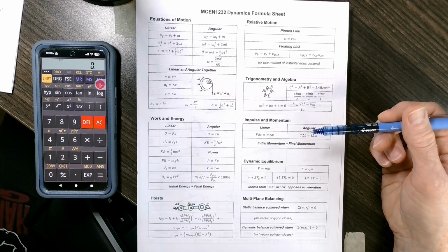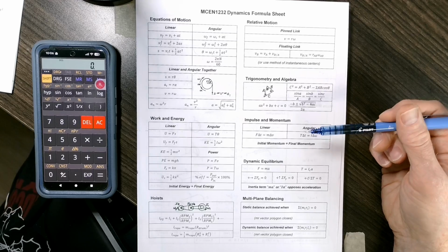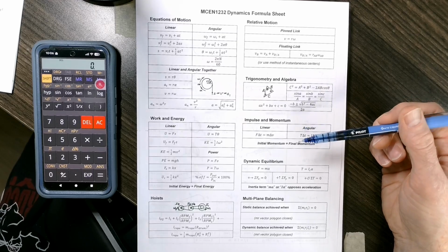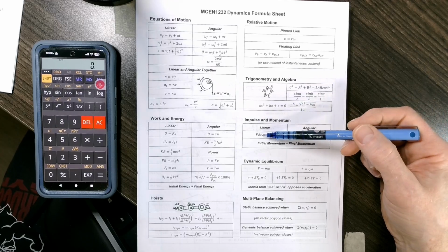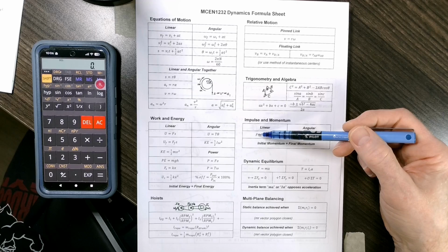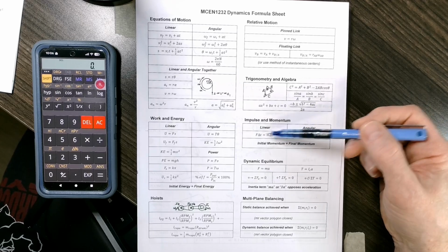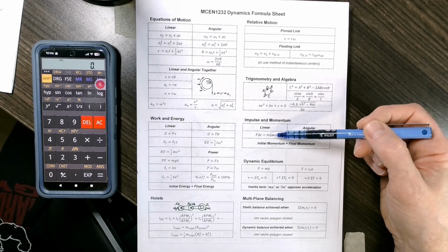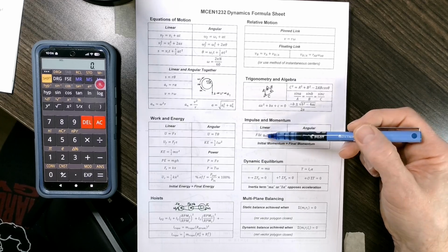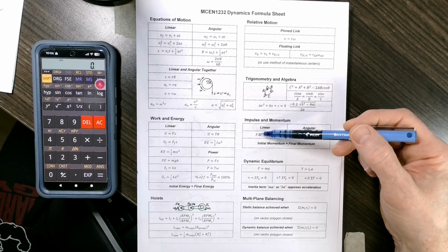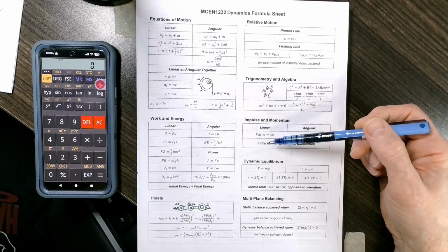But it depends what you have as known values entering the question. In impulse momentum, if you know the time and the velocity, and perhaps you want to know the force or something, those three are unknowns. The mass will be known. You're going to know the mass of an object. But of the four different values here, the performance metrics are velocity and time. The force is typically an applied force, a thrust force from an engine, or a braking force from a braking system, a drag chute or something. And mass, of course, is a property of the object.